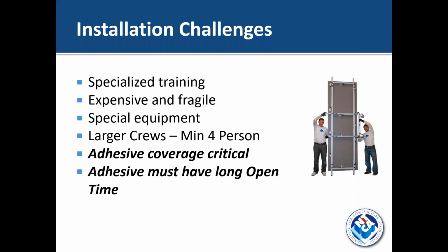In terms of an adhesive, the goal is to have a product that is loose enough to have ridges, so you can trowel it and preserve your ridges, but also an adhesive that enables you to easily collapse those ridges when you embed the panel, so that you'll get the maximum coverage. So most manufacturers have specific products within their lines.